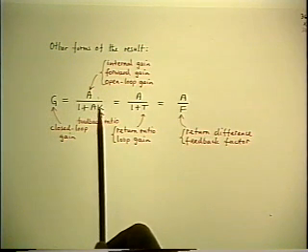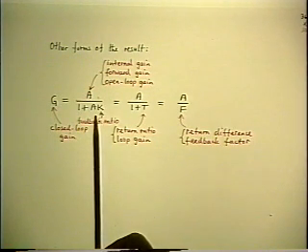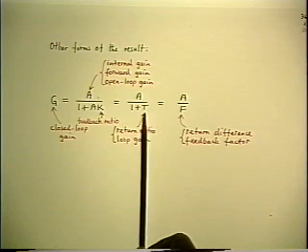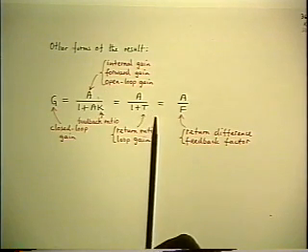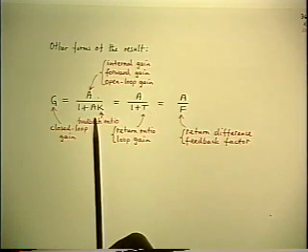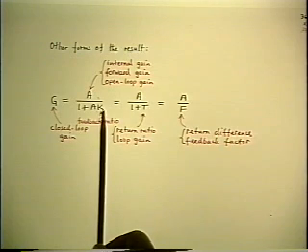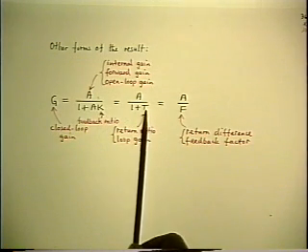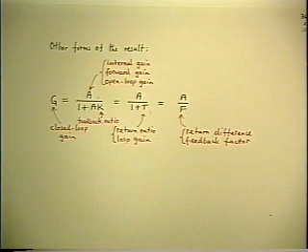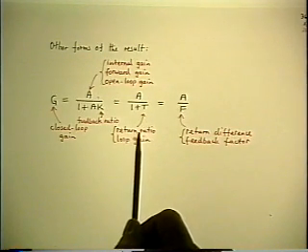But the product AK comes up so many times. Here it is already in the very first line. It has a symbol of its own, T. And I like to call it loop gain because that's the direct physical interpretation. If you start at an arbitrary point in the loop and follow the signal around to the other side of the same point, then you have to go through the product of those two boxes, and so that's the gain back to the same point, which is the reason why it's also called return ratio. The ratio of the signal that returns to a certain point in the loop to the signal that starts out at that point.